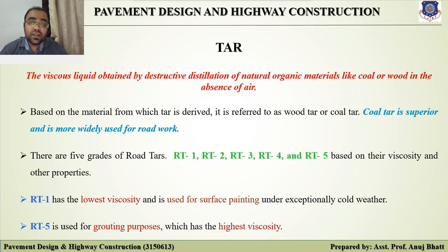Asphalt is less adhesive, whereas tar is more adhesive than asphalt. Asphalt is more durable as well as weather resistant, whereas tar is less durable and also less resistant to weathering conditions. Asphalt melts when it gets heated, whereas tar becomes more fluid when it gets heated.